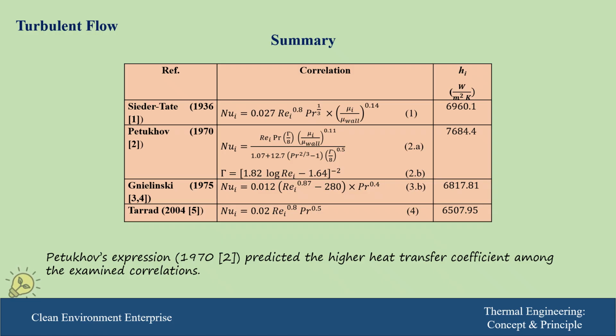Therefore, this correlation, as shown in equation 4, was obtained by the best fit to the experimental data, and it's clear that it predicted lower value since the data collected was from using a surface condenser that is used for a long time, and it seems to be that the scale which is found, or the fouling resistance existed, and it seems to be more practical than the others.